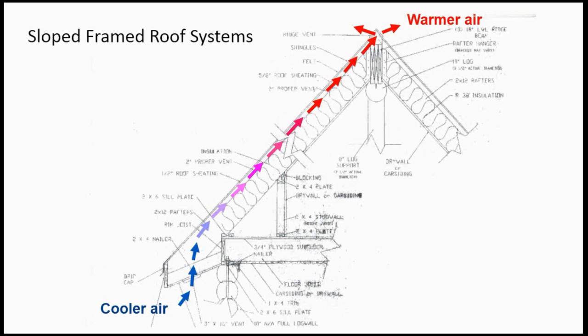And I can't stress that enough, because if it's 20 degrees out and it's 100% relative humidity, and you warm that air up to 70 degrees, that's only 15% relative humidity. So looking at the relative humidity obviously means nothing when you're talking about cold air.